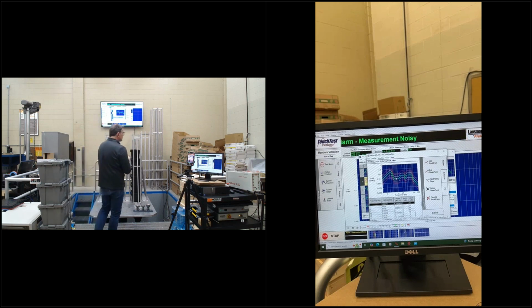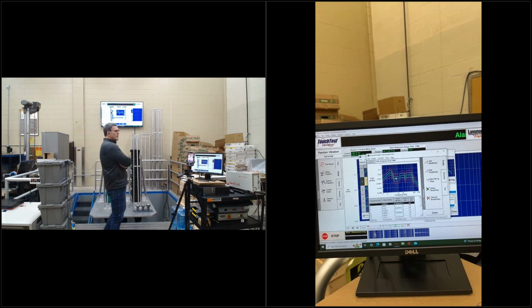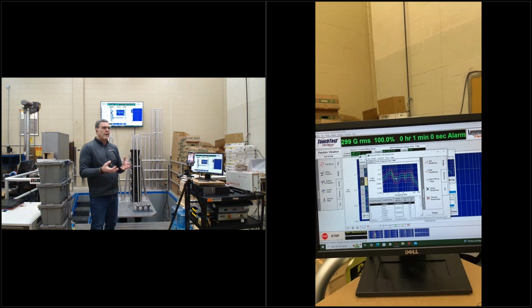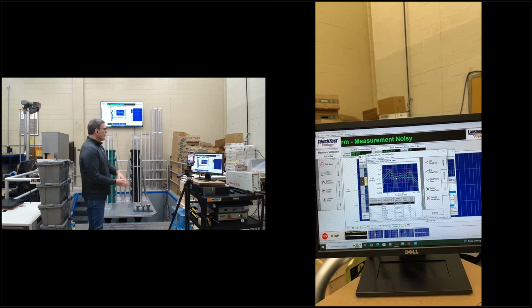In that video, those were pallet loads of paper towels, which you can think of as the product, but you can quite frankly imagine that's a soft, compliant load for the most part, adds softness, almost like cushioning, right? But what does that mean? Even with all that, you think of it as cushioning, but does the product almost have its own natural frequency response, so that, because of the mode of transport, with some of these peaks and valleys, it actually acts like a spring and makes the response greater at low frequency?